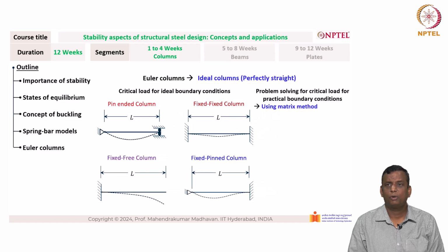And these are all ideal boundary conditions, but in reality, most of the structures do not exhibit perfect simply supported condition or perfect fixity. We need to understand that practical columns do not follow ideal boundary conditions. So we need to understand solving critical load for practical boundary conditions, which can be done by using what is known as a matrix method.